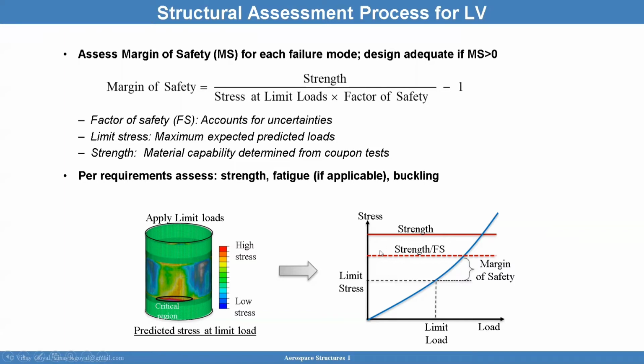And so what you want to make sure is that for the strength divided by factor of safety, there's space between that dashed line that's red and this black line that's dashed. And so this is your margin of safety here. We want to make sure that that margin of safety is greater than zero and perhaps even 10% to keep some pocket margin. Again, very, very important application that we're talking about, right?